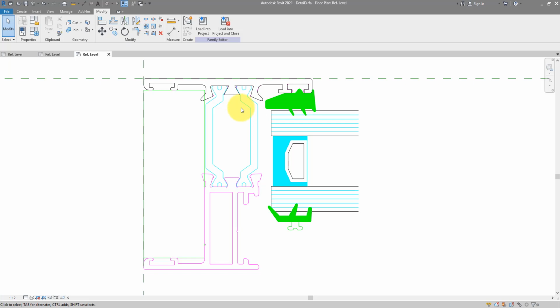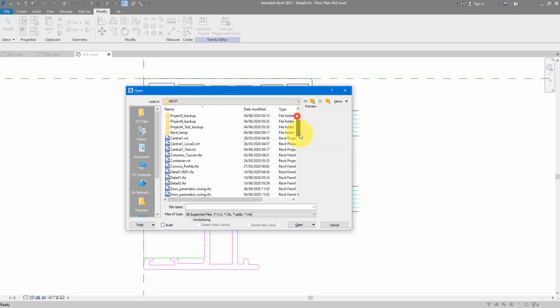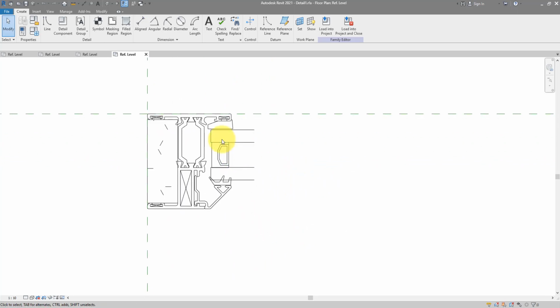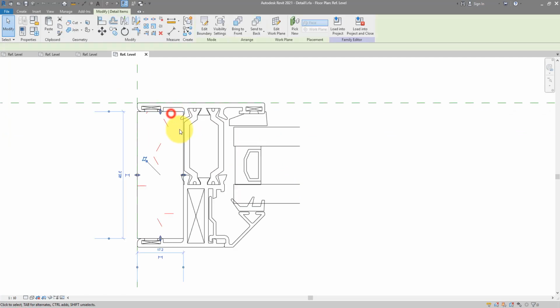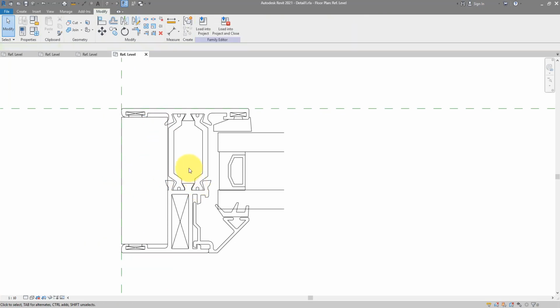Depending on the detail item you choose from AutoCAD, this could be a lengthy process. So to avoid boring you to death, I will change to the other detail component that I have already created for this demo. It's under here. And then detail 1. So you can see everything is the same, except that I have finished picking my lines and also put in here a filled region. Actually, that's good to show. Let me just recreate this filled region so you can see the process.